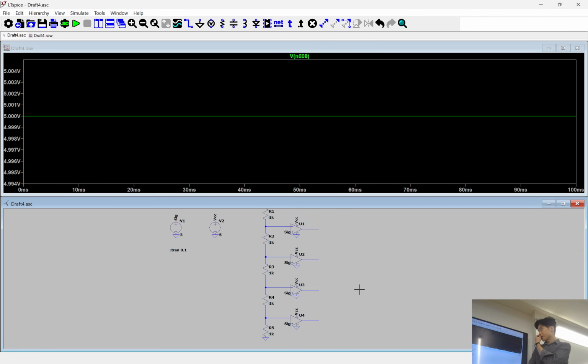Now, when it comes to representing this in bits, zeros and ones, we have 1, 2, 3, 4 comparators. So that'll give me 4 different possible levels in which my signal can be. If I have 4 different possible values, then one way you can think of that is that the data can be stored within 2 bits of data.